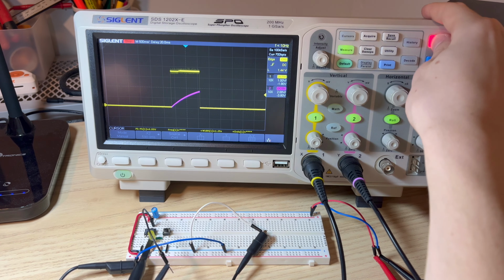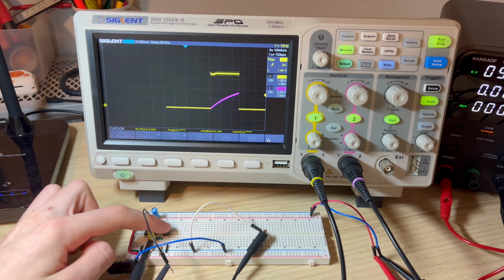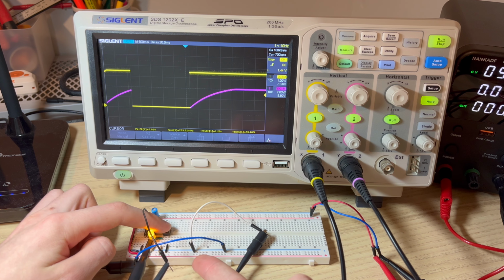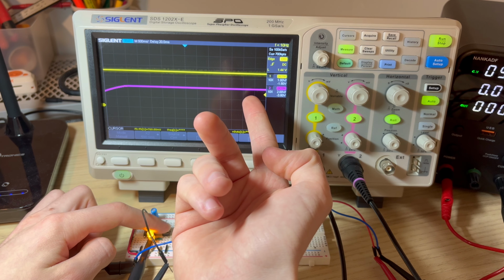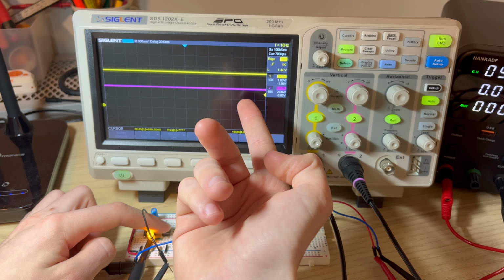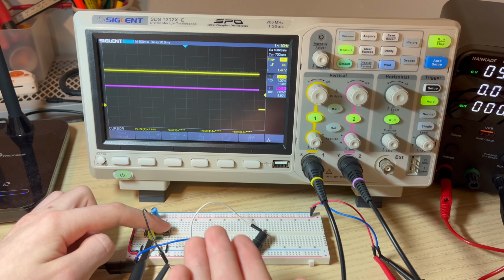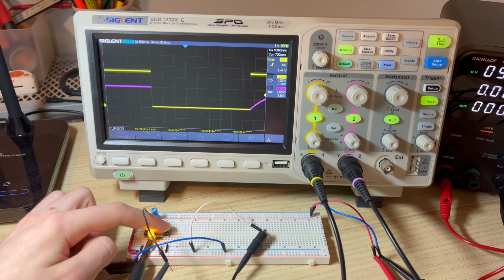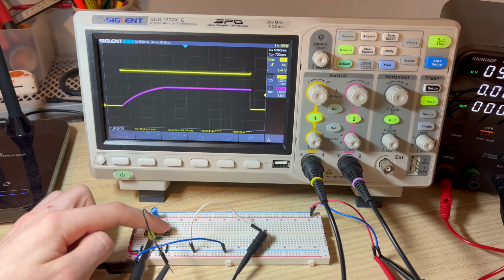So now if we continue this running, we can see signals there. One thing I do want to mention real quick is if we hold the button, you can see our output never turns off. That's because we're continuously connecting the capacitor to 5 volts, right? And so the output's never going to turn off. By holding the button longer than the actual time, it's essentially just acting as a debouncer now.